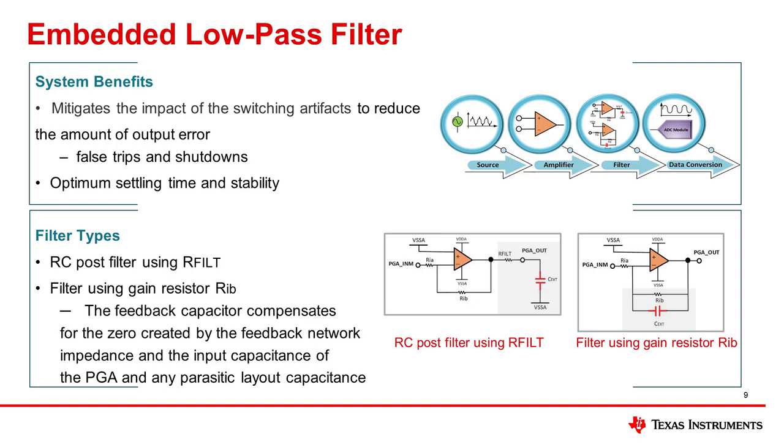As shown in the figure, the combination of an on-chip resistor and an external capacitor creates a low-pass filter that can limit the bandwidth of the ADC input signal. The user can choose the value of the capacitor to meet the cutoff frequency requirement to suit their specific needs.